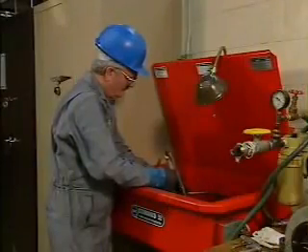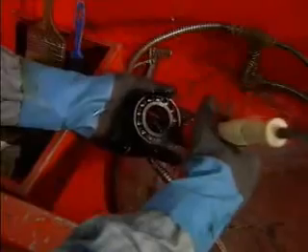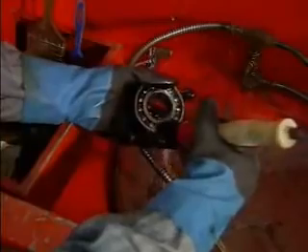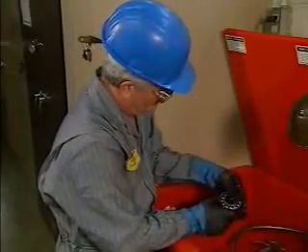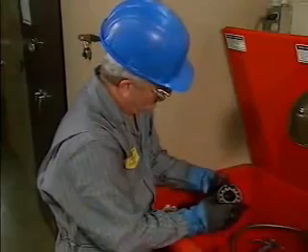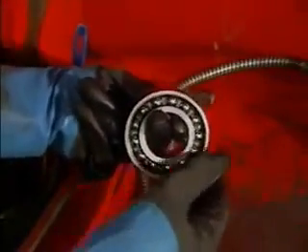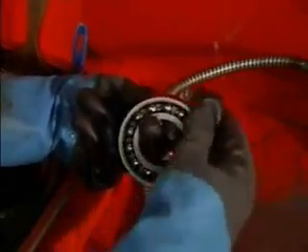In order to properly inspect the bearing, the mechanic must first clean it. In this example, the mechanic cleans the bearing with an approved solvent to remove grease and dirt. Then, after the bearing has dried, he examines the bearing for signs of failure. He turns the bearing slowly to determine whether there is any stiffness or binding when the rolling elements turn.